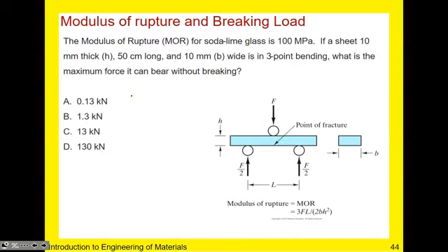So we won't go through this top hat question, but I just want to outline, if you apply a force this way with 2 counterpoint forces at this location here and this location here, we can calculate this modulus of rupture if we know the dimensions of your specimen.